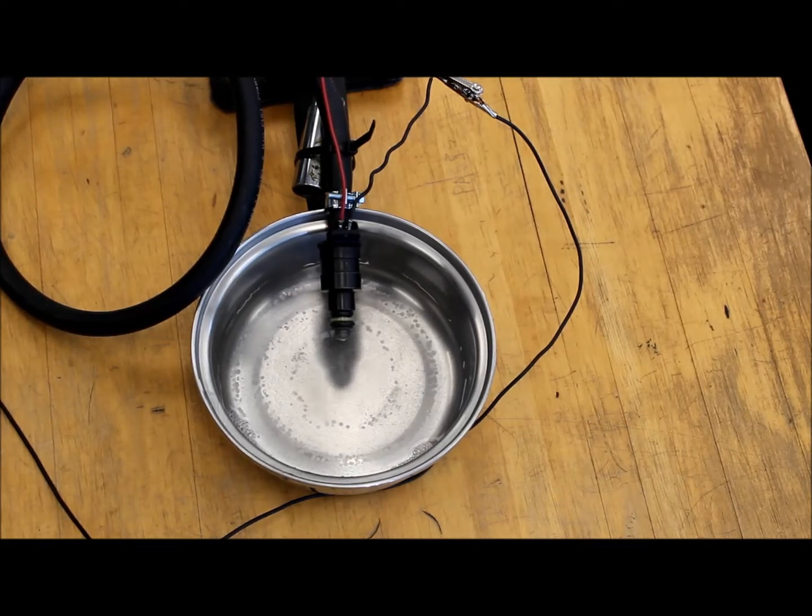And turn it off. And back on. And back off. So you can see when you energize the injector, it opens the valve, and the gasoline, normally, in this case it's water, that's supplied to the inlet of the injector, comes out the outlet, sprays into the intake manifold, or on newer injectors, of course, directly into the combustion chamber.